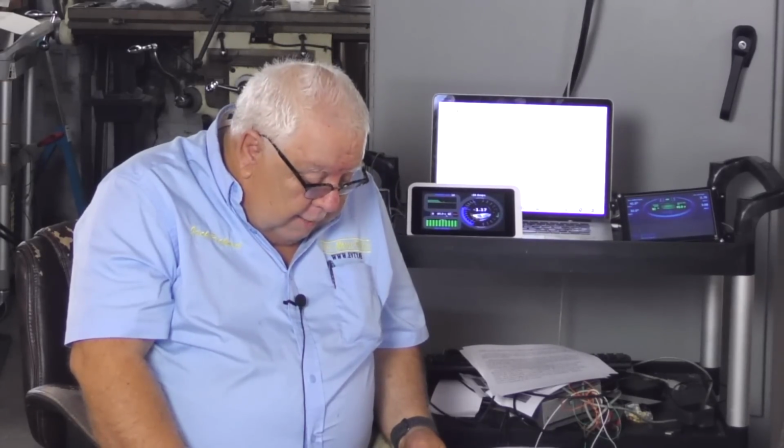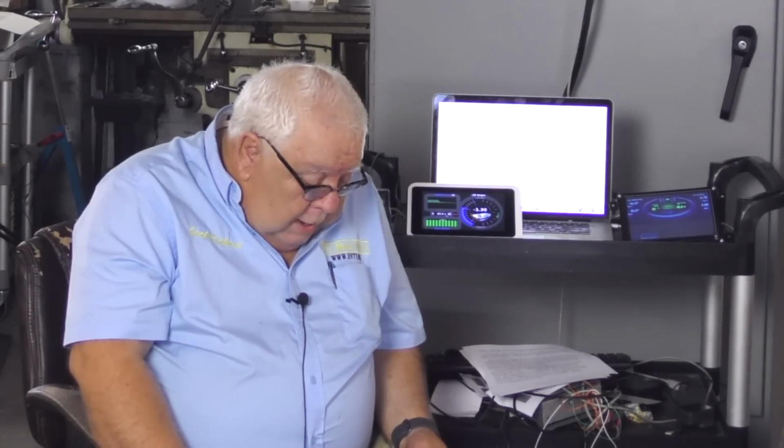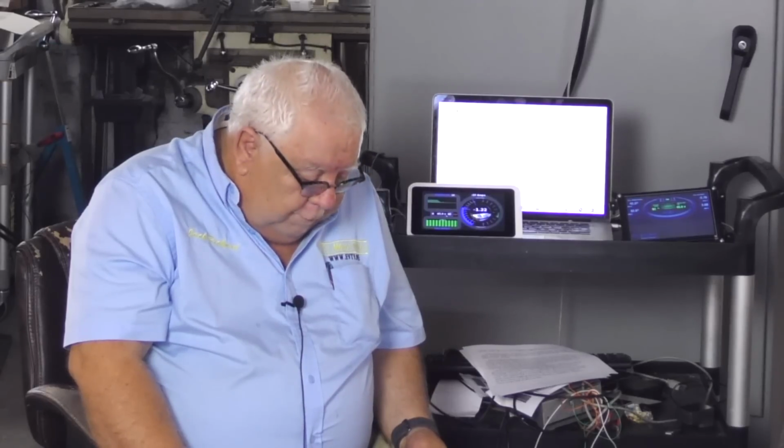But when we started charging using the AC input, and I do have a little trimmer pot on the inverter that you can actually modulate, but who wants to charge at a lower rate? And so we charged at 110 amps. That's about 4,000 watts at 39 volts, and maybe 5,000 watts by the time we get up close to 50 volts.